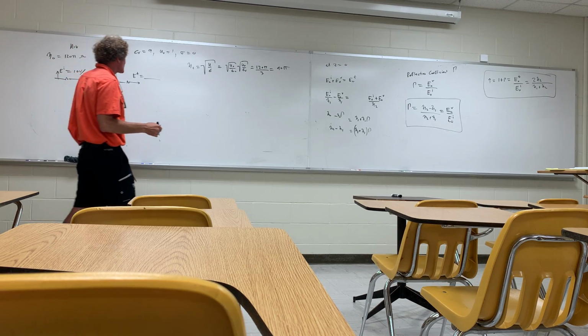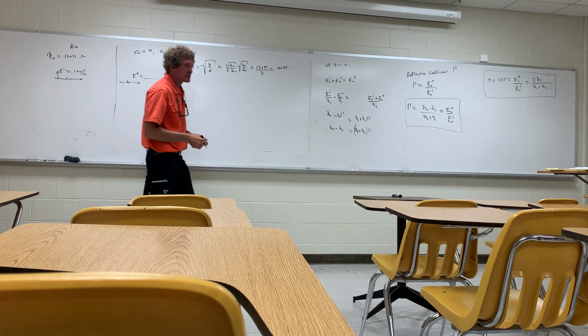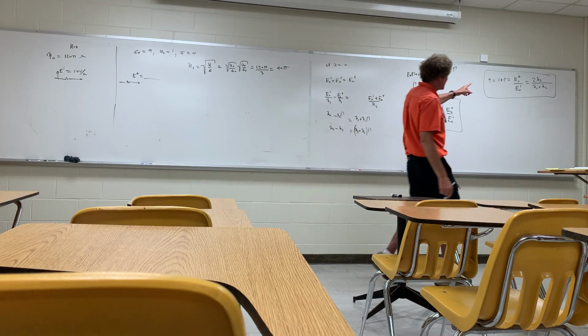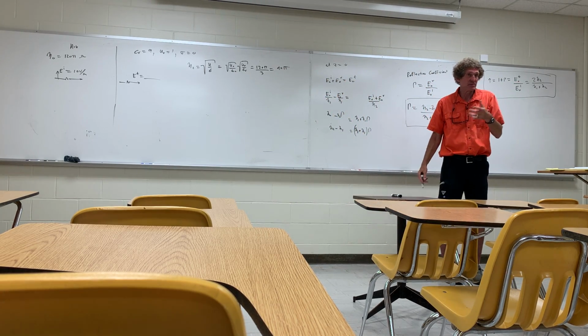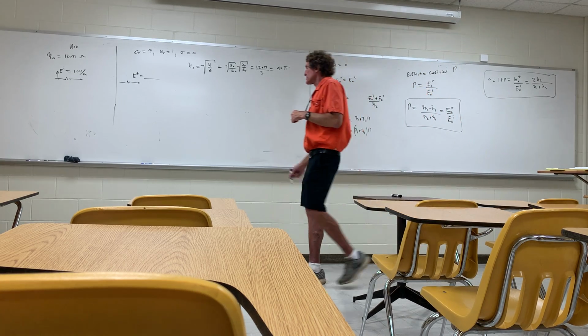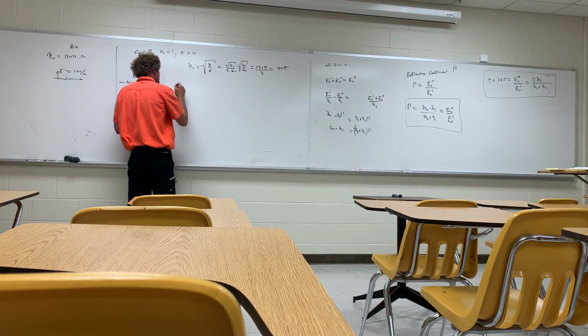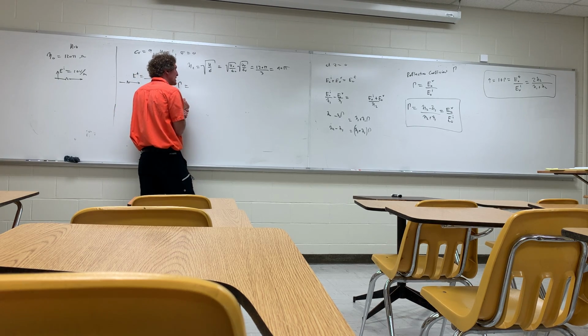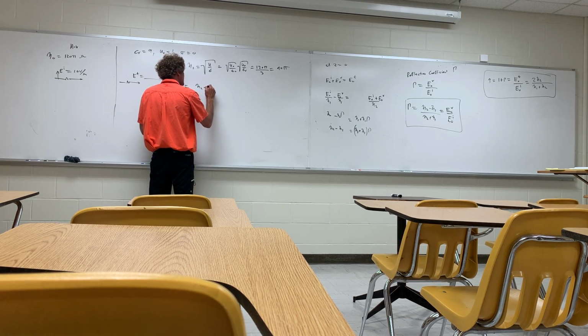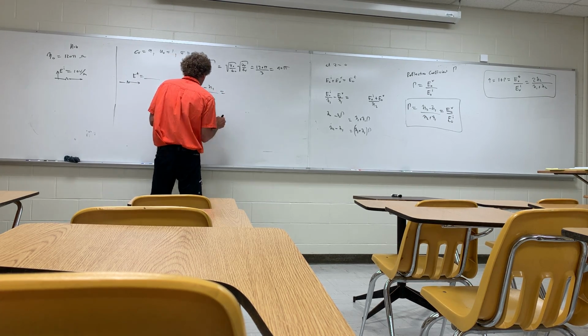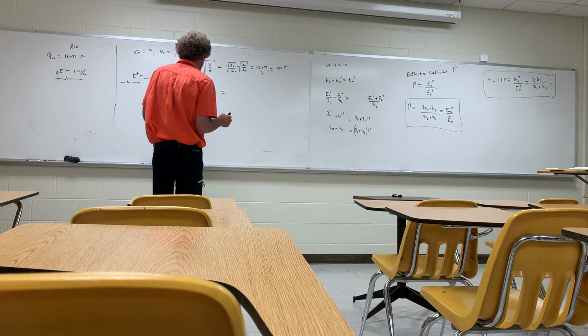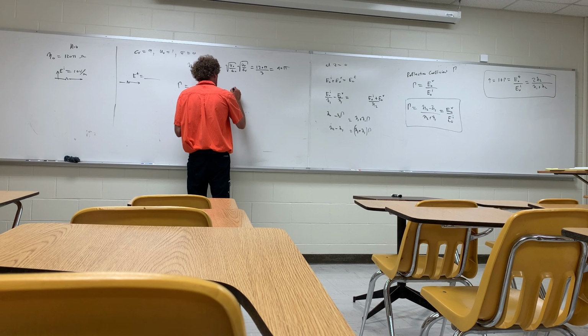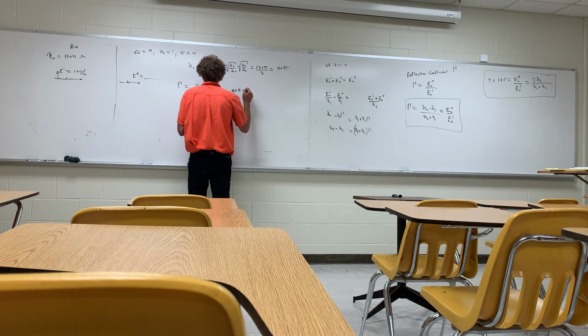Okay. So, now look, we can get the reflection coefficient first, and then add 1 to it, and we'd have the transmission coefficient. Doesn't matter, right? Why don't we go ahead and get the reflection coefficient, since we're interested in that. It would be eta 2 minus eta 1 over eta 2 plus eta 1, right? Equal, take a look at this. Eta 2 is 40 pi, right? Minus eta 1 is 120 pi, over the sum of those, which is 160 pi, correct, class?